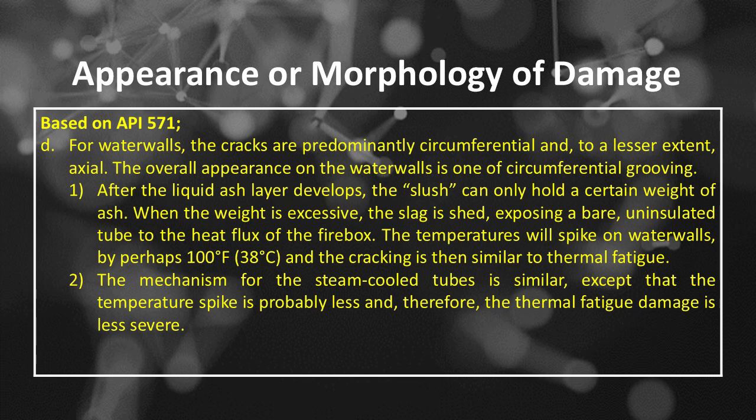Number 1, after the liquid ash layer develops, the slag can only hold a certain weight of ash. When the weight is excessive, the slag is shed, exposing a bare, uninsulated tube to the heat flux of the firebox. The temperatures will spike on waterwalls, by perhaps 100 degrees Fahrenheit or 38 degrees Celsius, and the cracking is then similar to thermal fatigue.